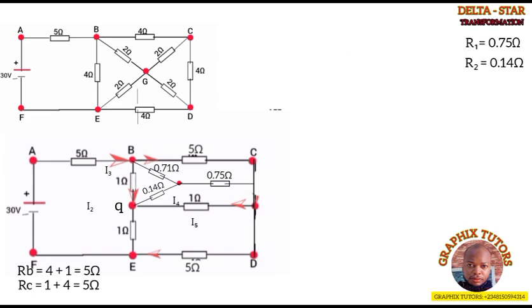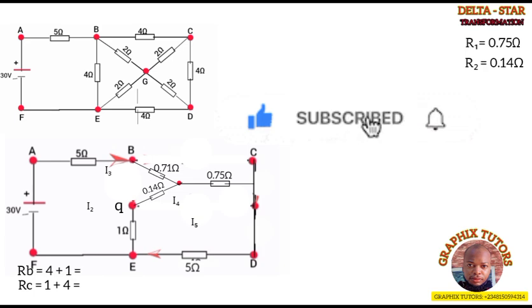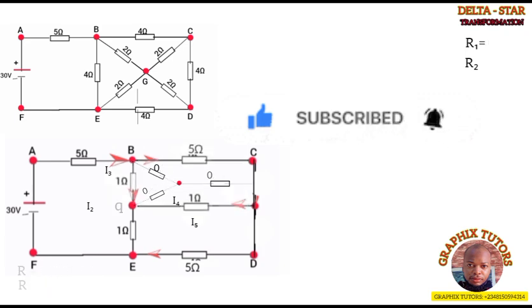So we've calculated for my R1, R2, R3, meaning that you remove the outer shell. So you do away with the 5 ohm, the 1 ohm, and the 1 ohm. So you'll be having a connection in this manner. Can you see that? So this is my delta formation, and I've transformed from that delta to star formation here. So you can see that.